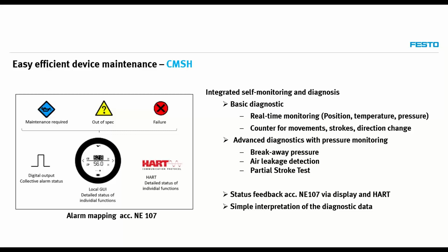Also, we have an intelligent diagnostics function with an integrated pressure sensor for monitoring, for example, the breakaway pressure of the process valve or leakage detection of the complete system. For the status feedback, it can be seen through the display or through the HART interface as simple diagnostic data. So anybody can understand the diagnostic data and determine the issue. For example, if we have air leakage, we can understand that we are facing some issues.